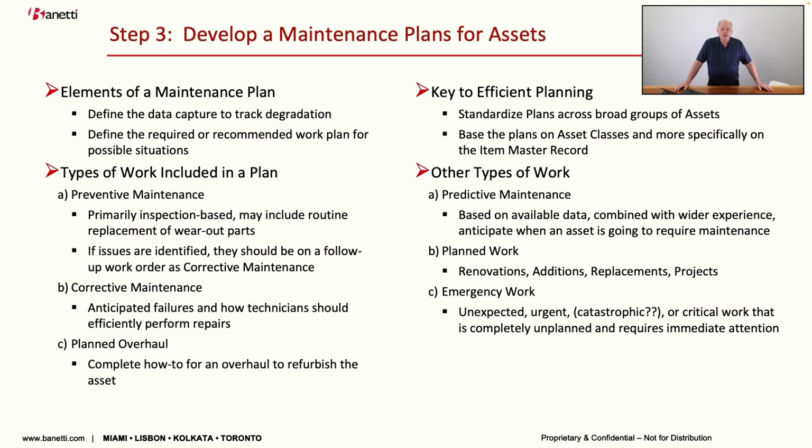And then planned overhauls are also part of it. If you're going to take that motor offline and rebuild it, what exactly are the steps that are entailed? And what parts do you need? What tools do you need? And how much time is it going to take? That can all be part of your work plan.